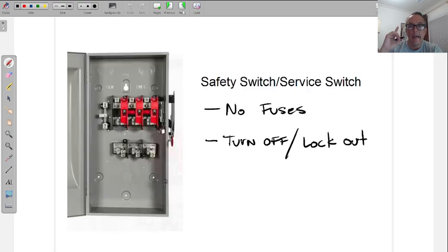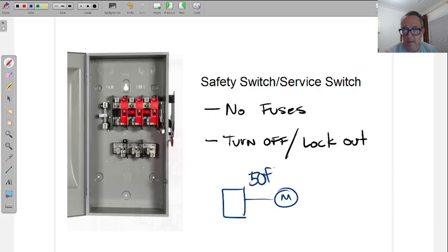I'm not going to go to the article, but it's in Article 430. I used to have it memorized, like 430.18 or something like that, or .20. It says in that article that every motor, 1 horsepower or above, must have a means of shutting off the power located within 50 feet of the motor, and I have to be able to see the switch, the off mechanism.